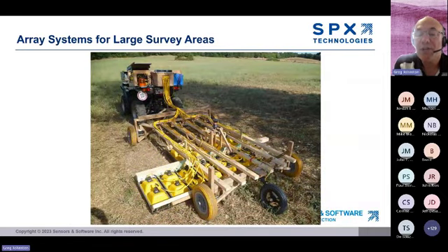Since that survey, various groups around the world started collecting data with multi-channel GPR systems to cover a wider swath and speed up data acquisition. This is a SPIDAR system that consists of 7 transmitter-receiver pairs of 500 megahertz antennas. Multi-channel systems simply make acquiring data over larger areas faster and more efficient. Now, practically weekly, you're seeing amazing archaeological work from around the world collected with GPR.